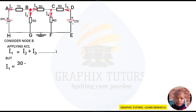If I take this point here, I'll call it V1, meaning that the current is going to V1. You can call it VB or anything. So the 30 minus V1, divided by the resistance in between those two voltages, right? And that is 7. So my I1 is 30 minus V1 all over 7. I will term that equation 2.